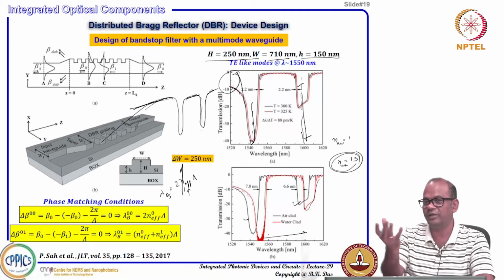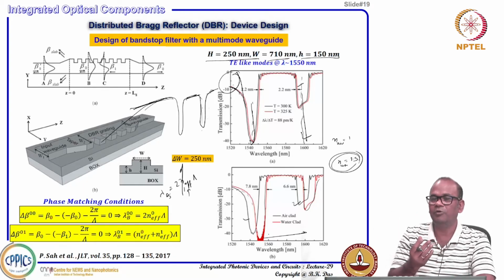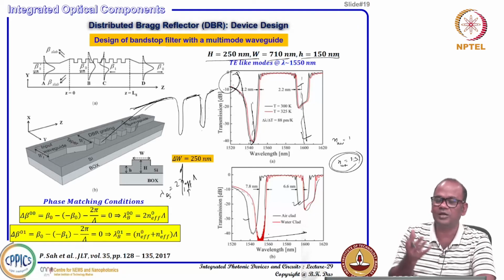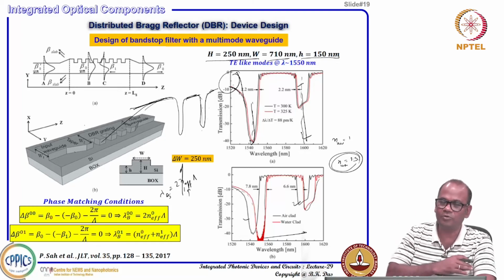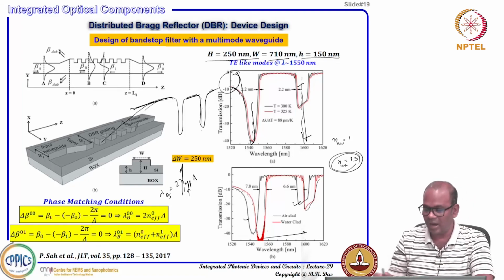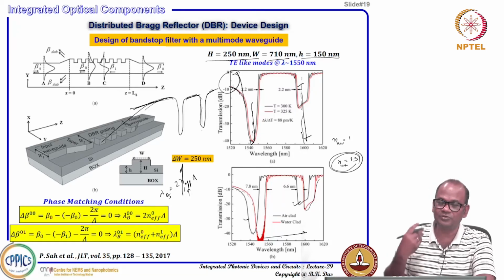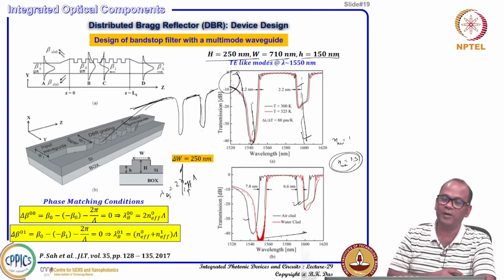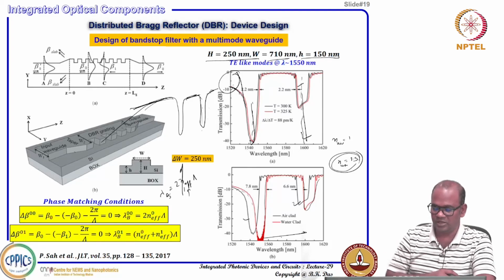Suppose you have a certain liquid that will have a certain refractive index, and you do not know what that material is. You can apply that liquid on the top surface as a coating, and then you see how much the Bragg wavelength is shifted. Looking at the shift, you can estimate and try to guess what material could be on the surface. So for biosensing applications and so on, people are demonstrating different types of DBR structures in the silicon photonics technology platform.